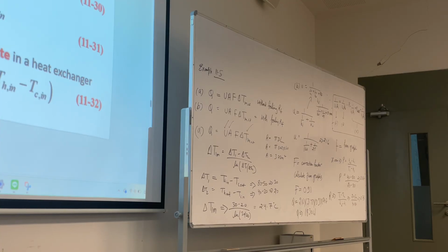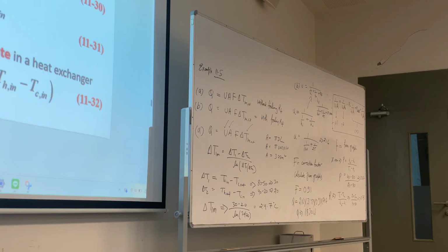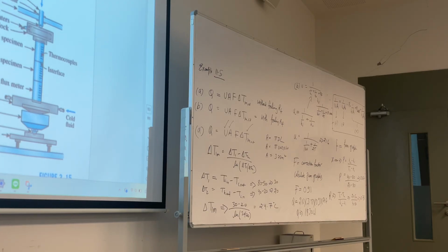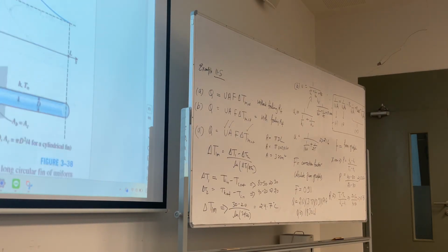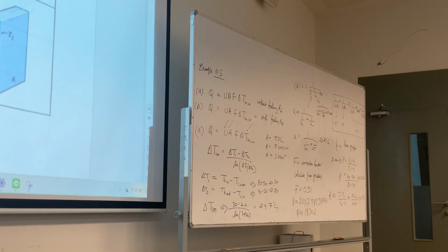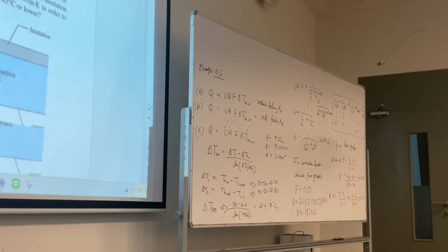When the outlet temperature, outside water or outside cold water is not given, then we use effectiveness NTU. Just like chapter 4, we were using some non-dimensionalized units, right? So we had non-dimensionalized temperature, we had non-dimensionalized time called tau when we were solving the Heisler charts. So similar to that, this is your chapter 3, and in chapter 4 we were using lot of non-dimensionalized.